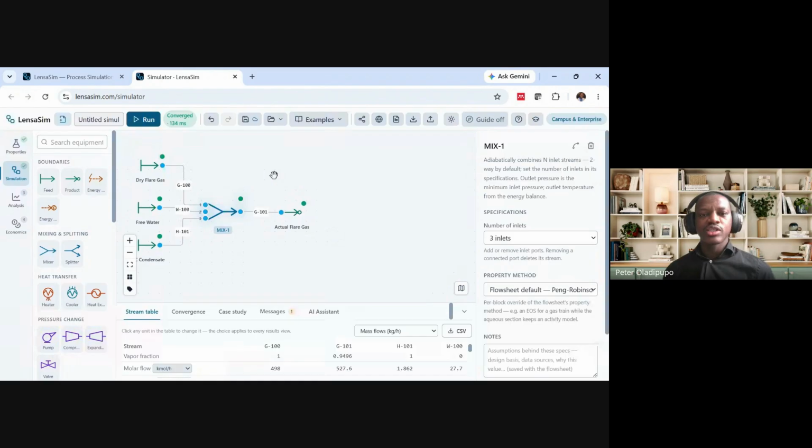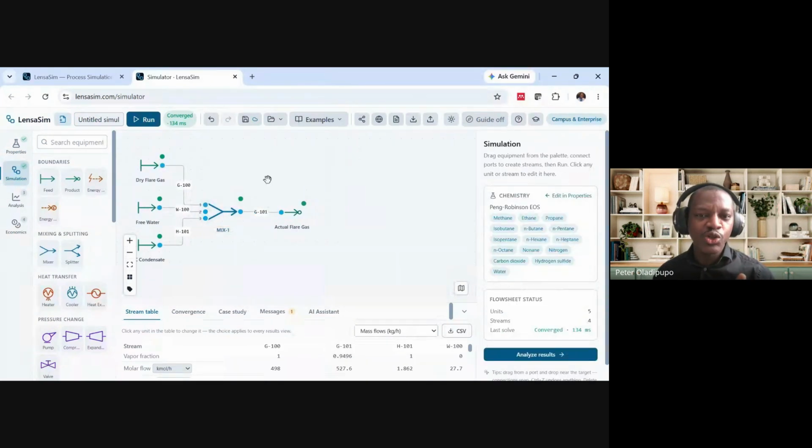Now the next thing is to start with the first proper process for this separation, for this gas conditioning. Essentially what we want to do now is the reverse of what we've just done. Okay, so in the industry, you use what's called a slug catcher to separate the liquid stream from the gas stream. Because what we have here in this gas stream is not just gas.